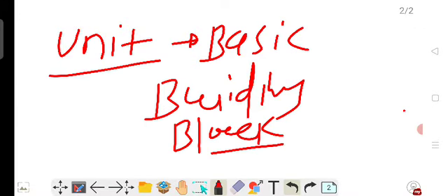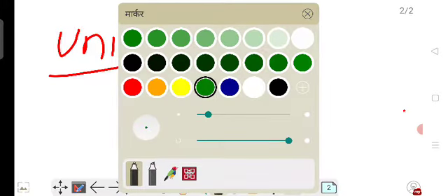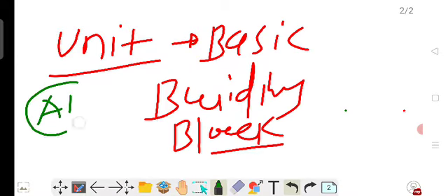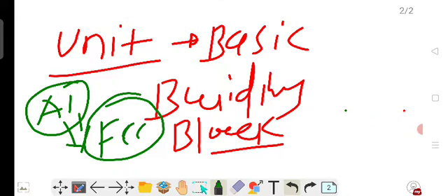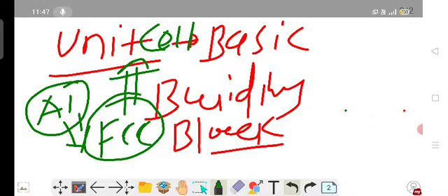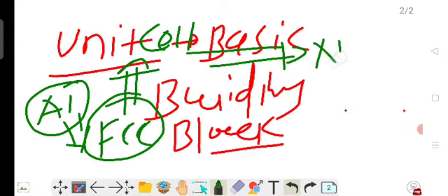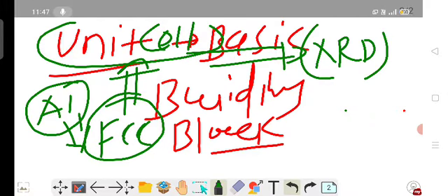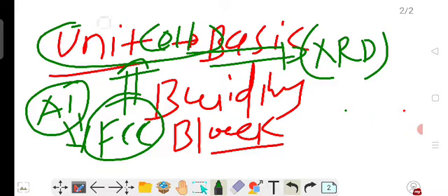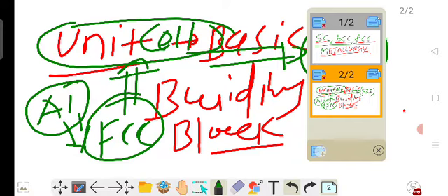Say for example, we have aluminum. It has FCC crystal structure. How do we get to know aluminum has an FCC crystal structure? We have to find out the unit cell with the help of X-ray diffraction, and if this unit cell is FCC in nature, then we say that aluminum has an FCC crystal structure. So let us discuss one by one.